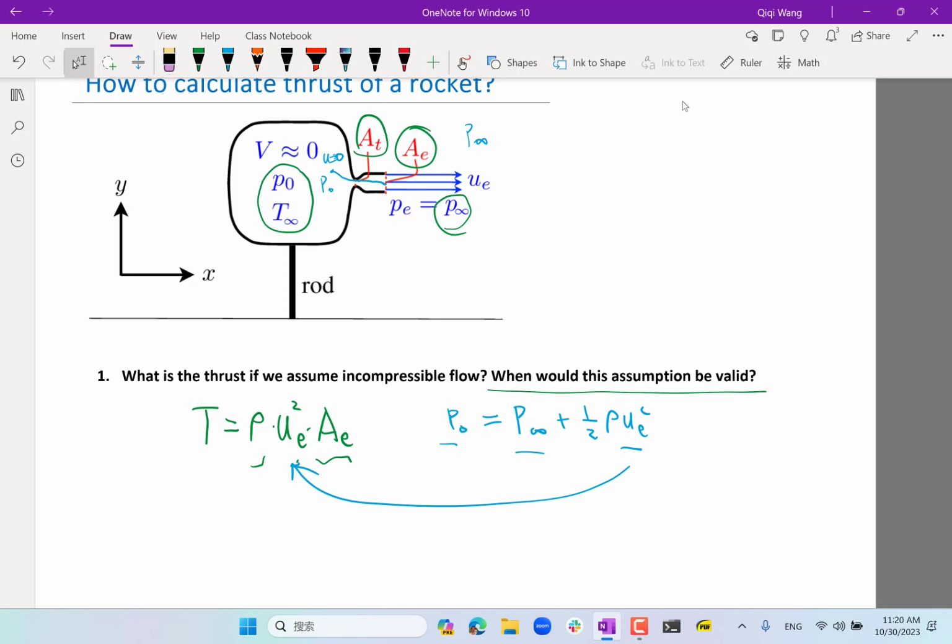Let me tell you one very commonly used strategy for dealing with compressible flow, which is to get the Mach number, and everything can be worked out from the Mach number. Specifically, it is most convenient to figure out the Mach number in a steady state flow. In this case it's trivial, but later you're going to see that you want to take a frame of reference in which the flow is steady state and figure out the Mach number associated with that frame of reference.